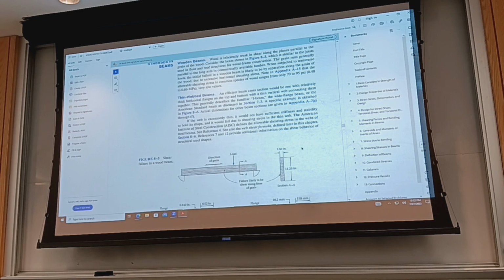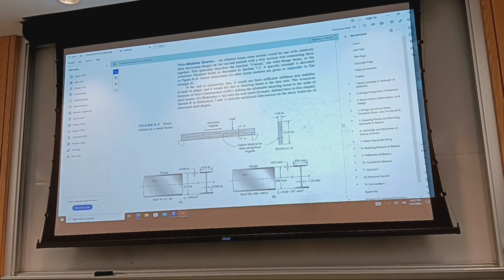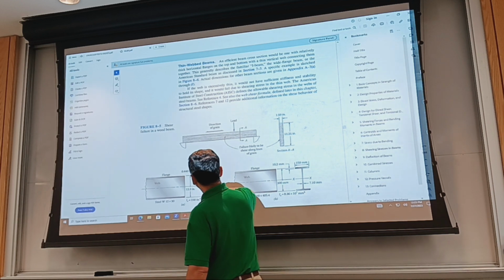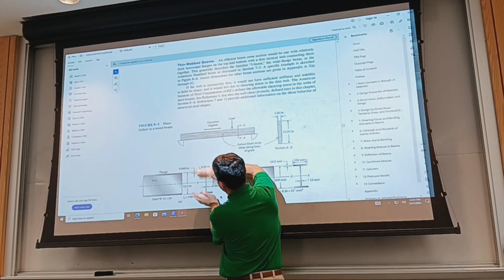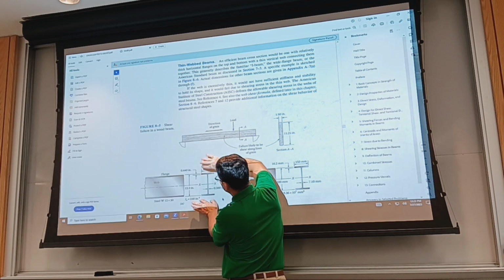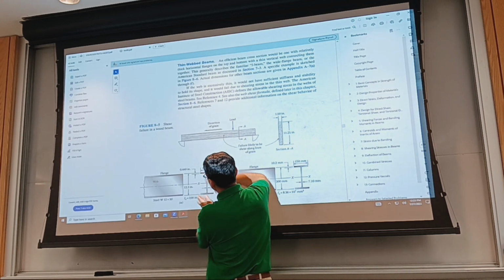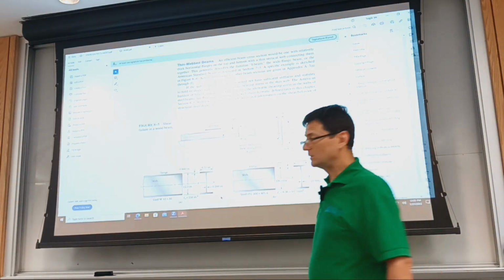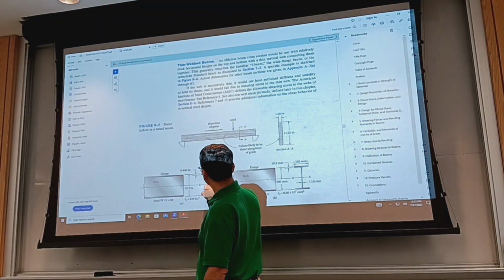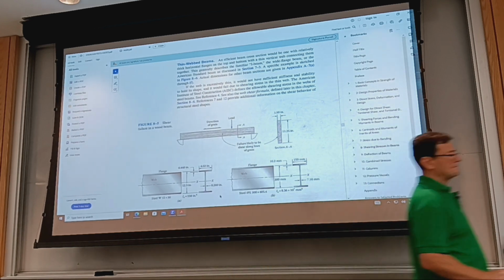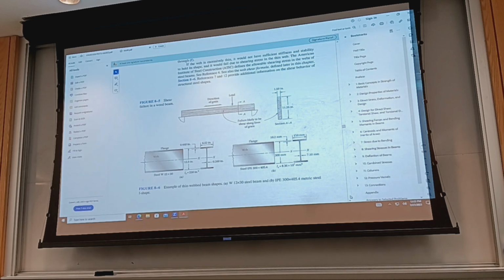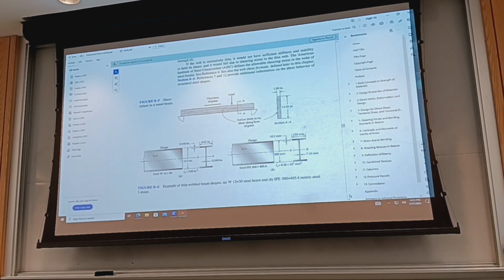If we have thin webbed beams, like wide flange I-beams with thin webs, things can happen. It's strong in bending. We move the material to the outside to maximize the area moment of inertia, and it goes down with the bending stress, but it can become weak at the web. I mentioned short beams. There are fabricated beams. Composite beams likewise are sensitive.